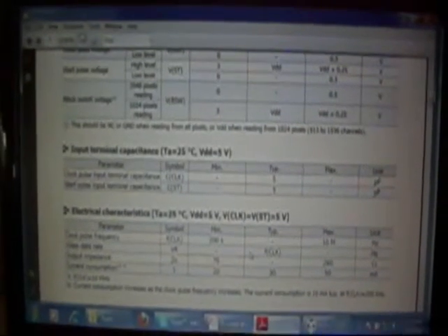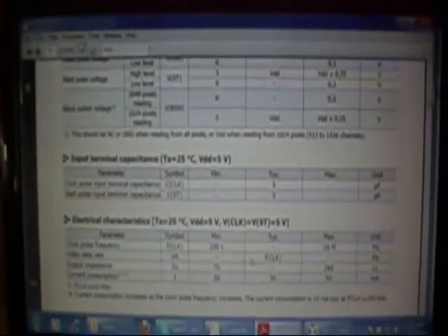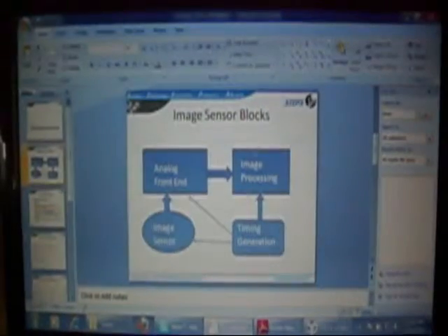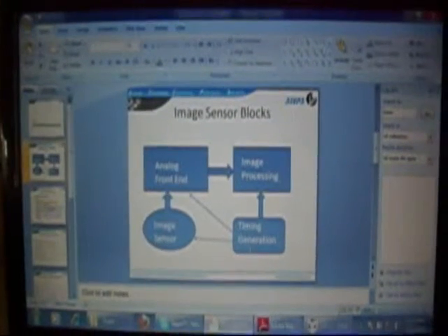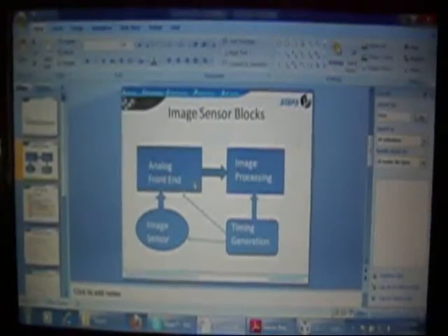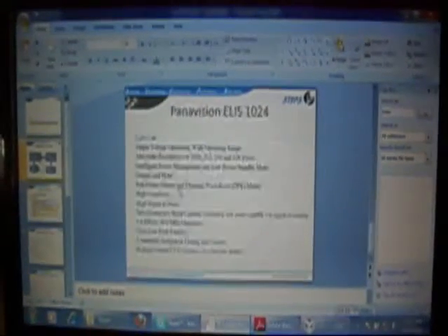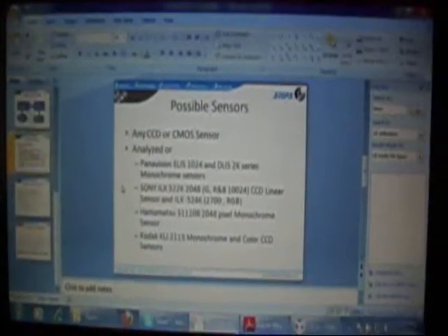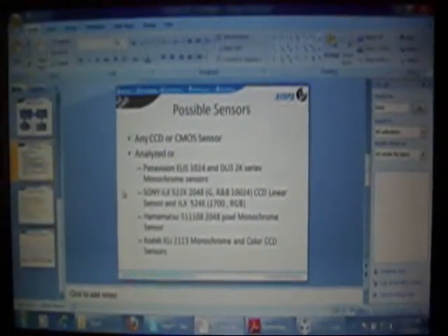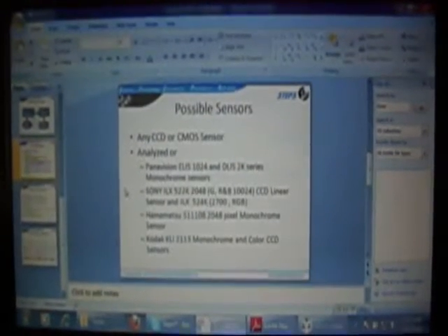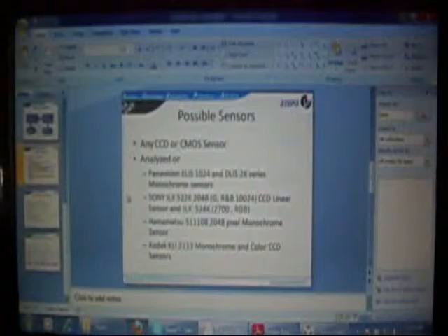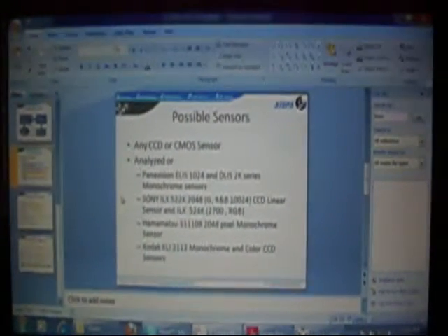The innovation here is to use the ARM Cortex-M4F as the single system on a chip for all the functional blocks. This would enable replacing a DSP, FPGA or a CPLD, which generally form part of the image processing and timing generation. All this is combined into a single ARM microcontroller, the Cortex-M4F. A small form factor, good processing power, affordable cost, lower power consumption and a very good external interface mechanism make the ARM Cortex-M4F an ideal choice.